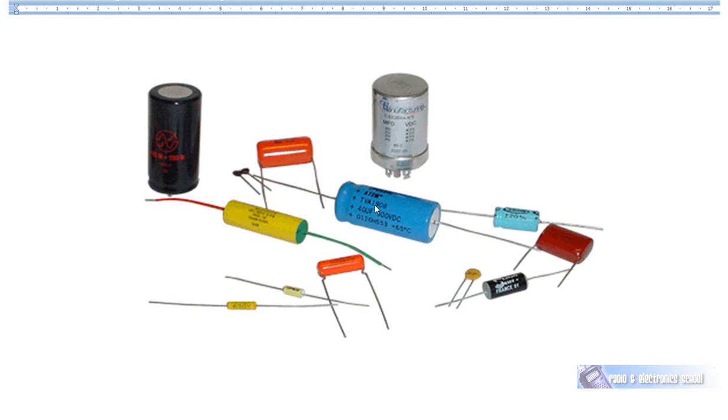This is an electrolytic capacitor, and they've got a chemical paste inside them, and that chemical paste is used to create the dielectric during manufacture. Should those capacitors be reverse polarized, that is, if you put the wrong voltage on the positive lead and the negative lead, they will explode.